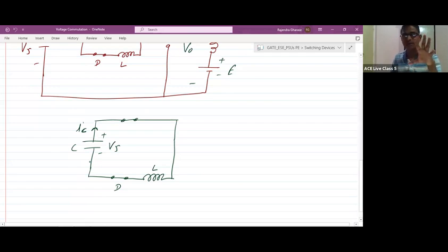Or, in the time domain itself, we add the initial voltage across the capacitor separately from the passive element, then apply KVL, and then take the Laplace transform with zero initial condition. In the Laplace transform we have the normal transform, and second, the property with non-zero initial condition.